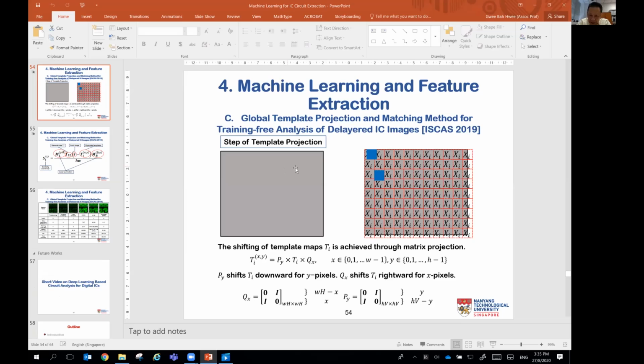We are looking at the particular image, whether it is actually from the template, whether you can find the template in the actual image, or whether there are any other parts that have the same component. So by using this method, you still need IC expertise, but it will cut out a lot of time in doing this counterfeit IC detection.